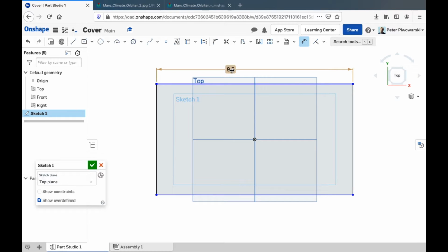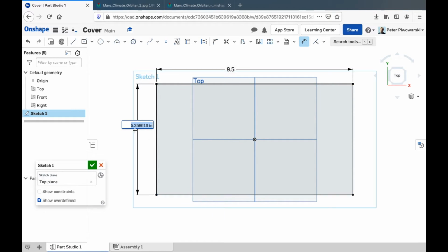So, unless you want your part to burn up in the Martian atmosphere, you should always keep your unit with your measurement. Whenever you see me type in a unit, I'm going to say IN for inches or cm for centimeters or something. And the reason it's useful to do this is, let's say instead of 5 inches for how wide this is, let's say I measured that in centimeters. I look at my tissue box and it's not quite 12 centimeters wide. So let's say I want to make it 12.5 centimeters wide.